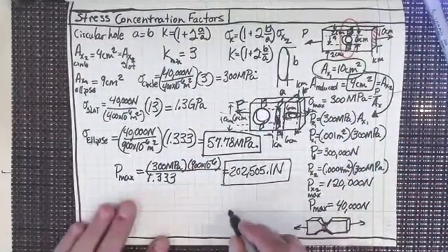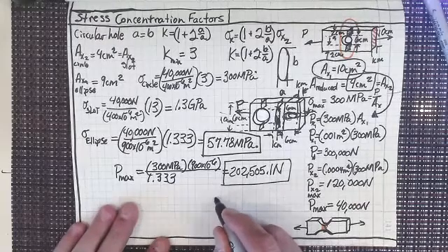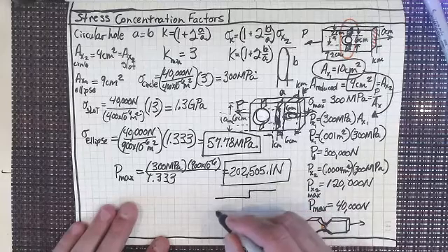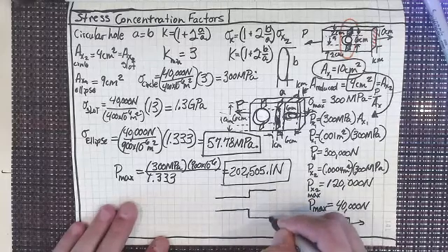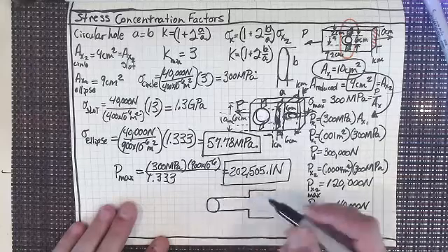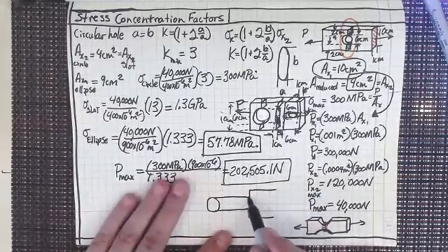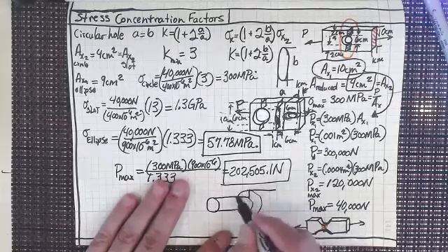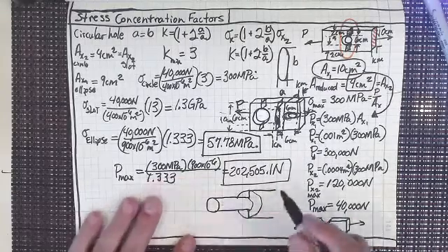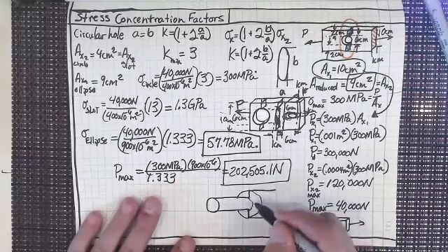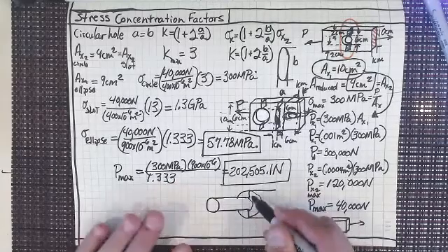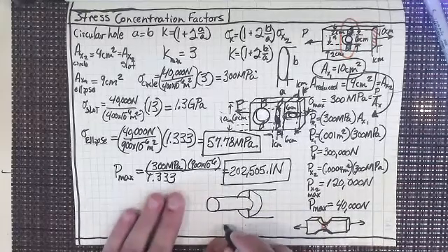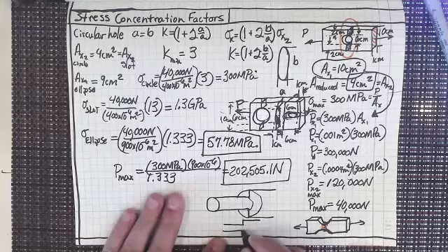Not only that, what if I had a torsion rod that had a discontinuity here, right? Isn't that discontinuity like infinity, right? Let's say that I'm torquing on this torsion rod, and I don't even know how I draw that. Something like this. Yeah, and so I'm twisting on this torsion rod, and I've got a discontinuity here, right? So that discontinuity at the top and bottom, that's where it's going to break, because if I look at this in cross section, I see that I have something like this.